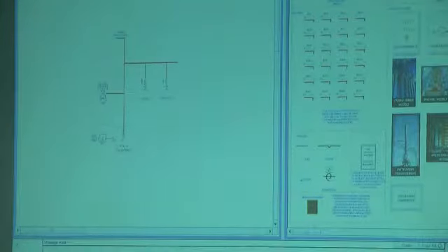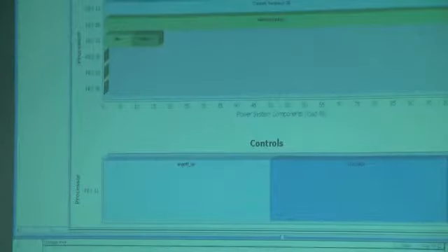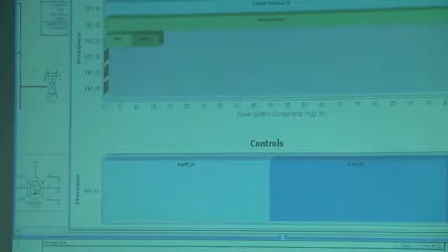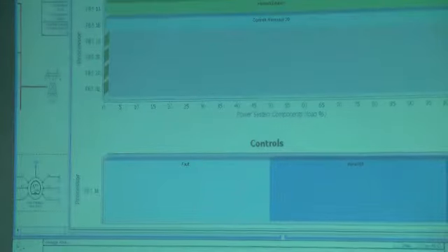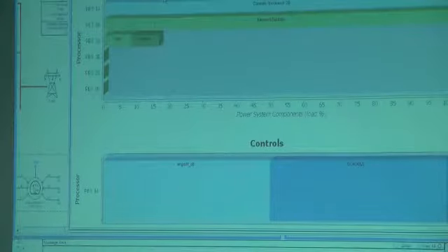So it compiles successfully. So if I look at my processor assignment, this might not be the best way to do it, because in subsystem 1, I have a T-line, a source, a network solution, and controls. In subsystem 2, I have a network solution and controls. So I'm actually using 5 processors for this simple network, which is way too many.